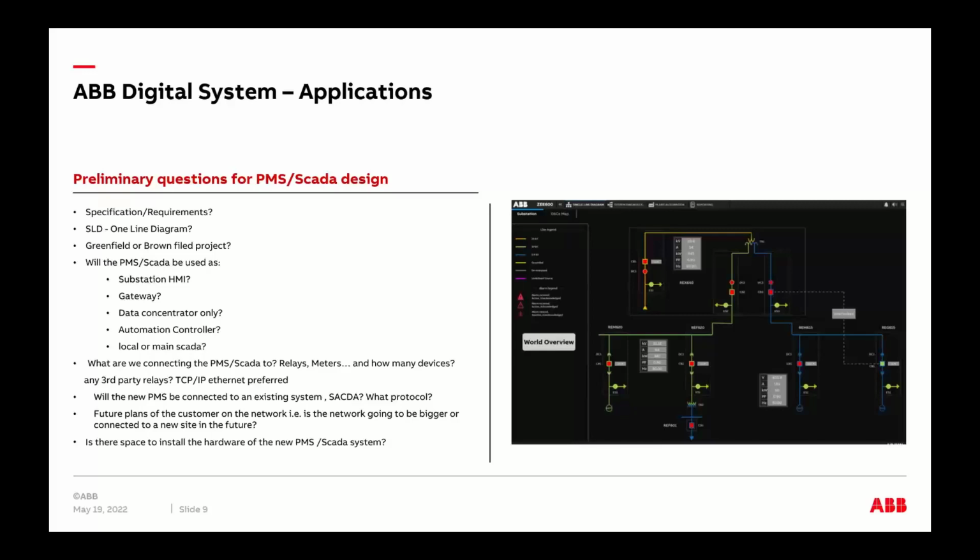Maybe your HMI is not only acting as an HMI, maybe it's also acting as an automation controller. Typically, we'll try to stay away from that. When you do this kind of digitalization of a network, you want your outside logic, your outside controllers, PLCs, anything automated to be an external device.